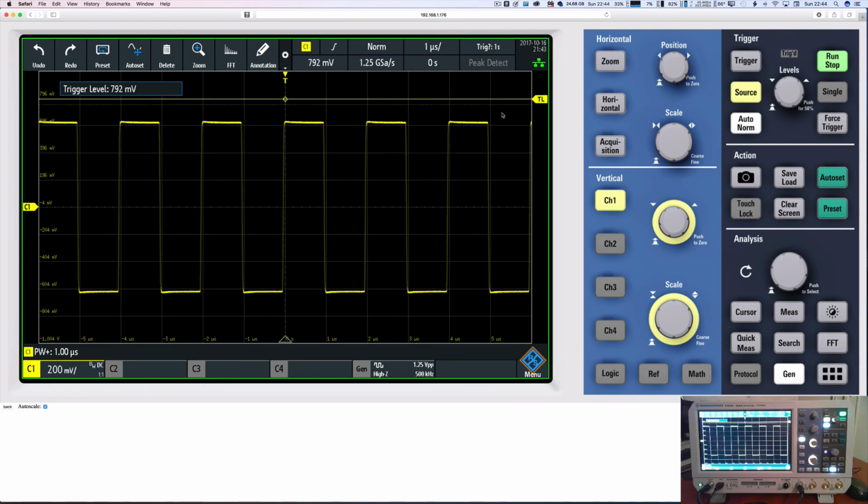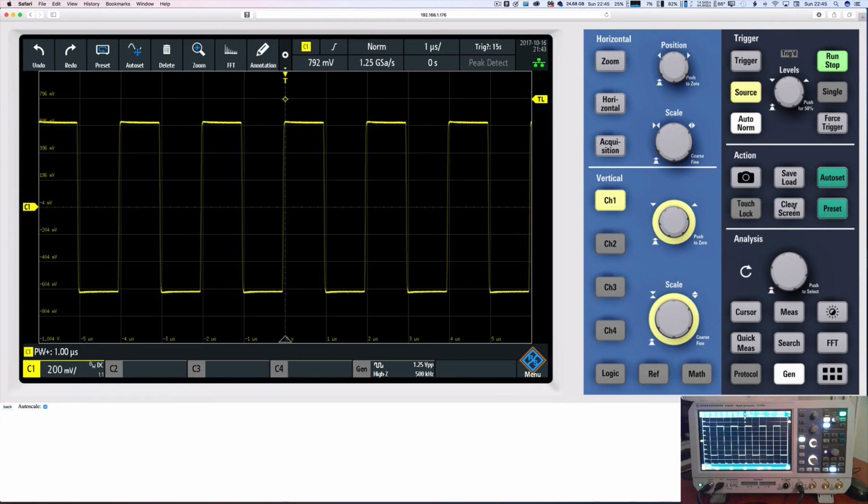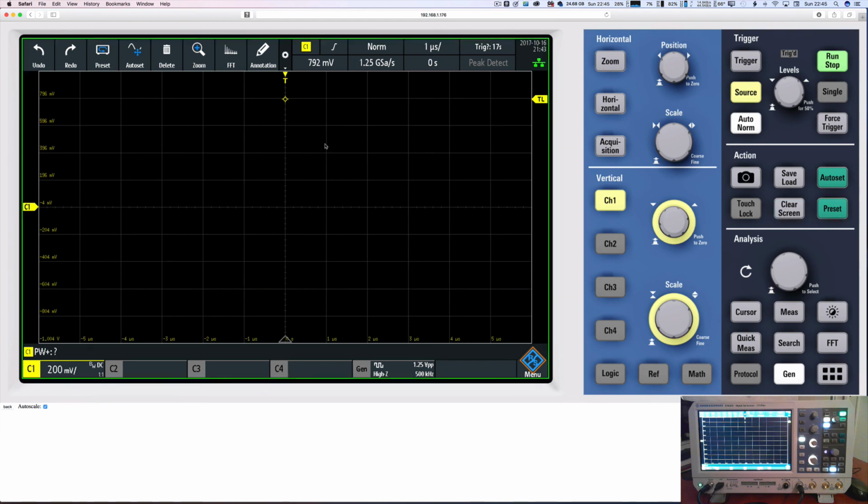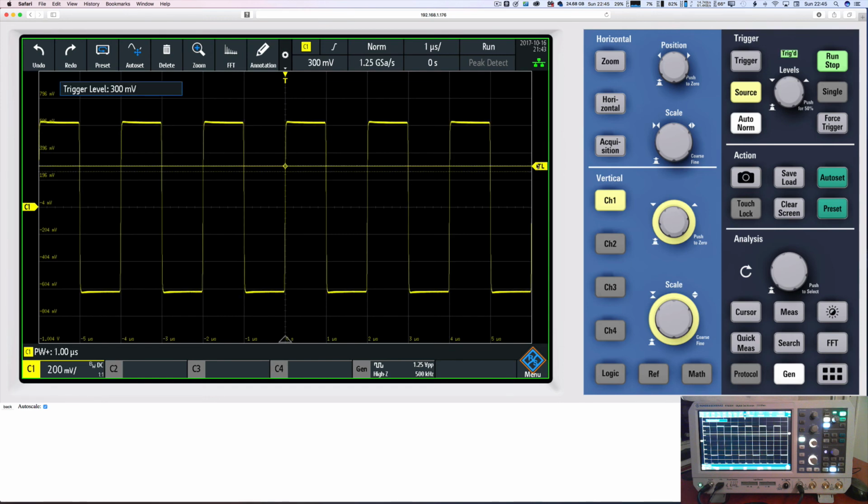I thought it was strange that it still had the waveform. I thought that would disappear, and I thought it was wrong. But in actual fact, reading the instructions, it actually remembers the last acquisition and kept it at that. So it was triggered when I took it above that, so it's now remembered the last. If I clear the screen now, you won't see anything. If I bring my trigger level back in, we're triggered again.